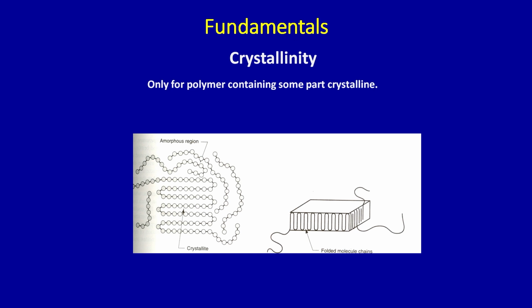And in polymers you can have both a crystalline part and an amorphous part together. Crystalline part means when these chains are arranged very nicely, you can see here one by one they are arranged parallelly. You can also have arrangements of haphazard molecules, that is what we call the amorphous regions, and this is very important in polymers, because most polymers will have both amorphous and crystalline regions, or amorphous regions predominantly. We will try to understand now what is amorphous and what is crystalline in detail, but I think I have told you about crystalline material.